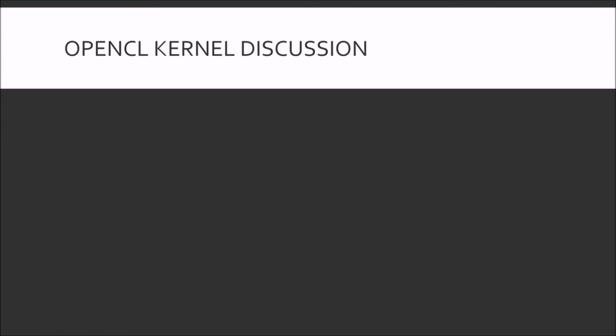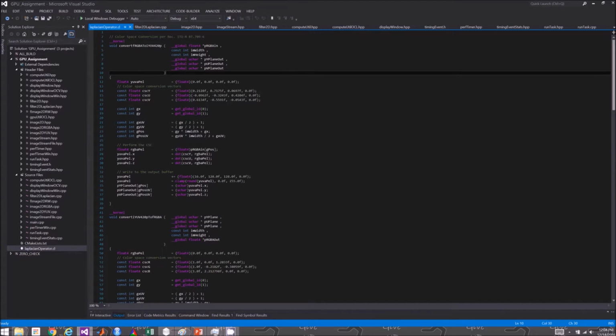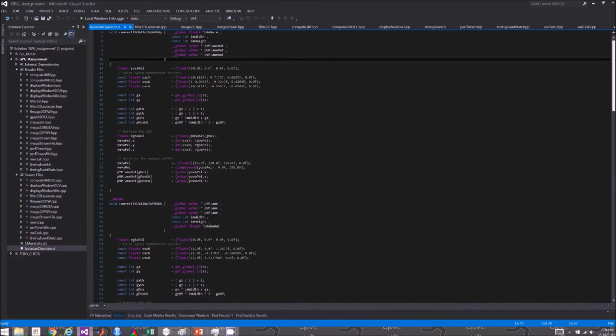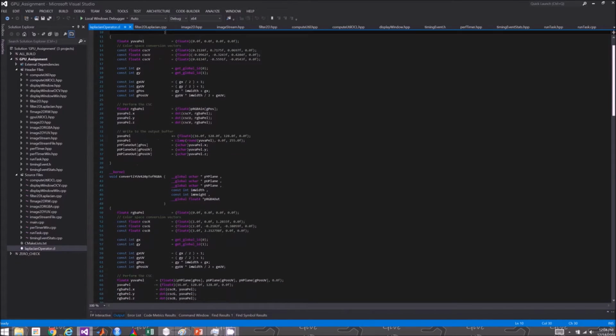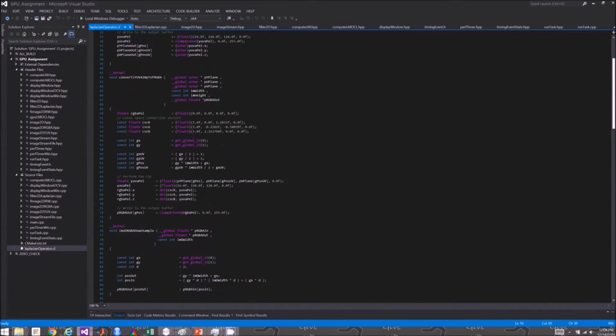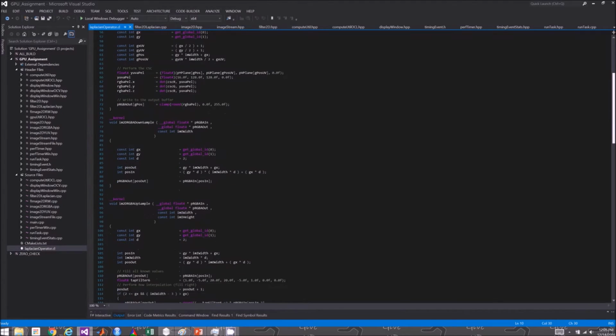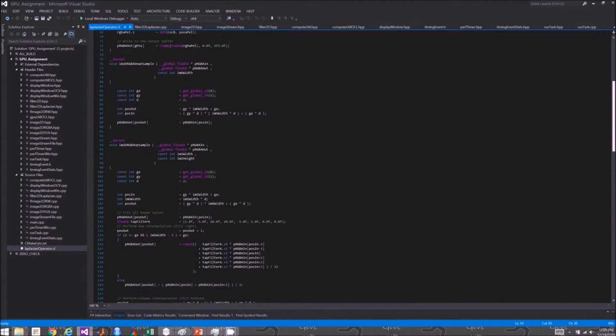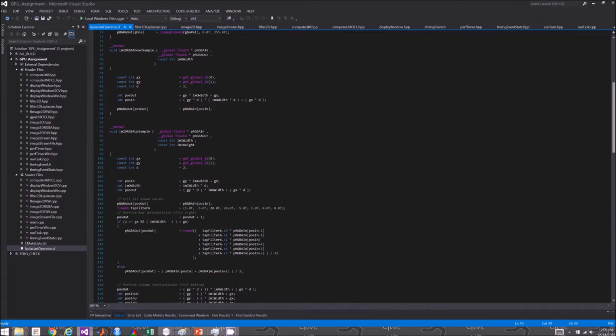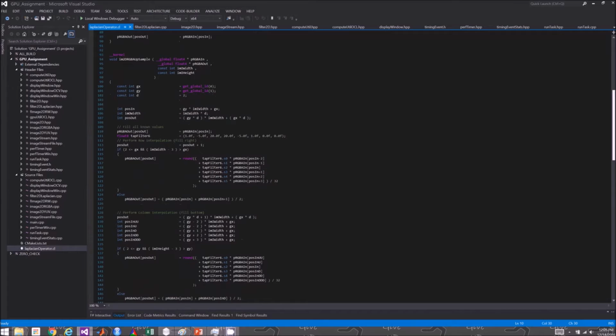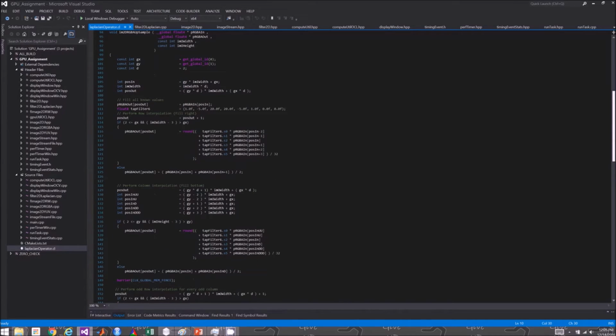We now turn our attention to our OpenCL kernels. We start by providing two kernels to provide color space conversion, one going from YUV to RGB and the other from RGB to YUV. This enables us to perform all of our convolution processing in the RGB space. We also have a downsample kernel and an upsample kernel. The downsample kernel is a simple decimate downsampling routine. The upsample provides a 6-tap interpolation filter in order to provide a better quality output for the upsampling by 2.